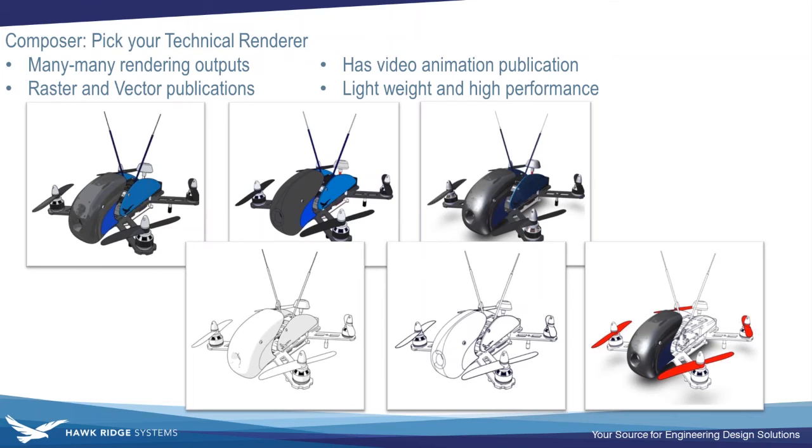This last one, I didn't really show how to do that in the software, but what you can do is per component, per part, you can choose which style you want. Basically how that works: instead of saying, hey, globally for all the models here, we're going to have this shaded technical drawing, you could say, hey, this part is shaded, this part is silhouette, this part is technical styled, and then you can create these really cool outputs to really define areas of the model. It's really great for assembly instructions, so you can say, hey, the red parts are moving right now, we're assembling them, now we're going to assemble the green parts, and so on.